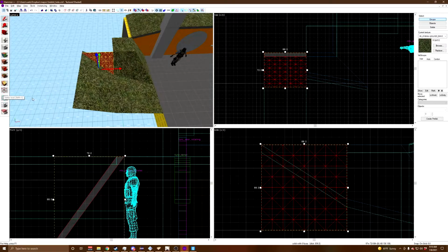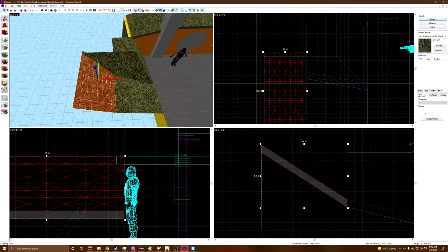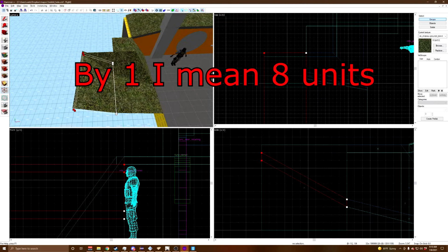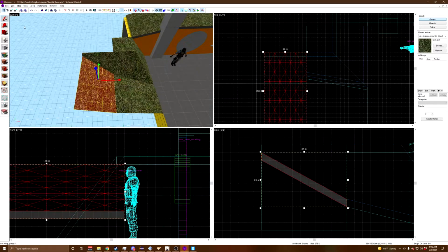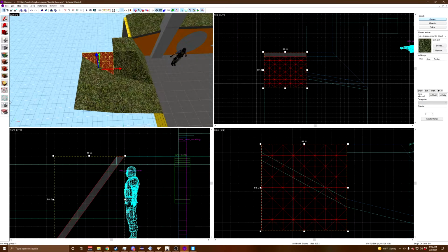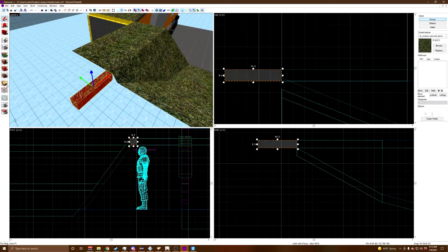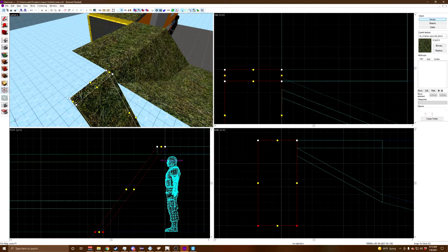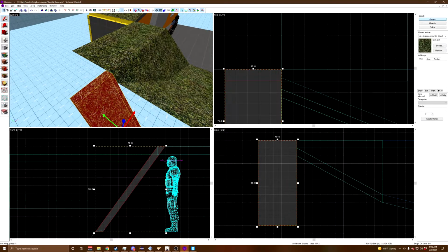Well, it's a little hacky and there's probably a better solution for it, but this is how I managed it. First, I lowered the slope of the hill by 1 so that there's still room for a fourth side. We can now complete this section as normal. I will now create my final wall piece for this hill. I'm now going to use the vertex tool to drag the bottom 4 vertices down into the side so that it matches the slope of its adjacent wall.